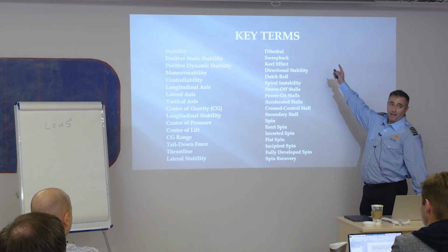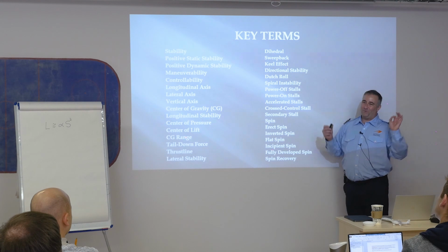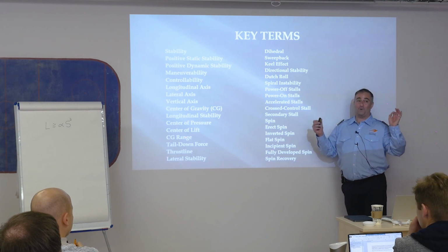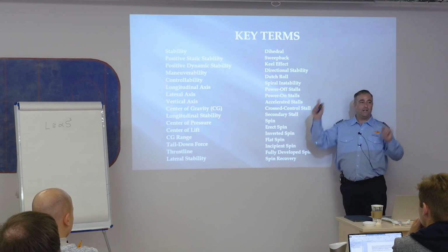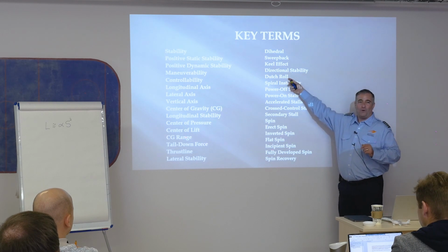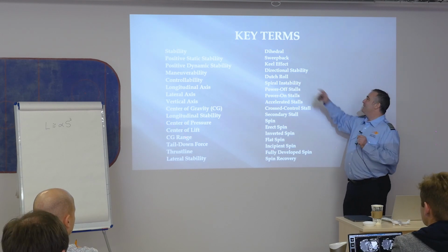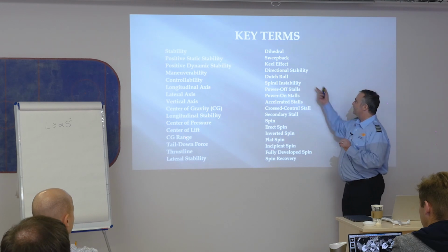Lateral stability with dihedral. Sweep back. When you start flying one, we'll get a lot more into it. Right now, we'll probably just take a picture of it and then see how it works with a yawing motion. Directional stability, Dutch roll. Dutch roll is fun. And how do I avoid a Dutch roll? Well, I fly the airplane coordinated for sure.